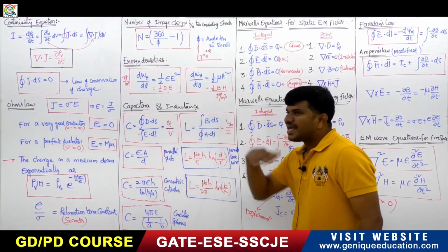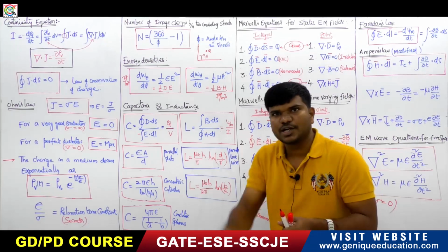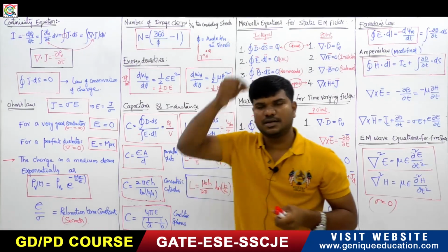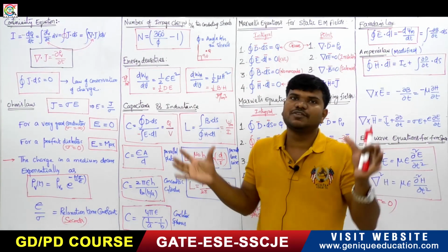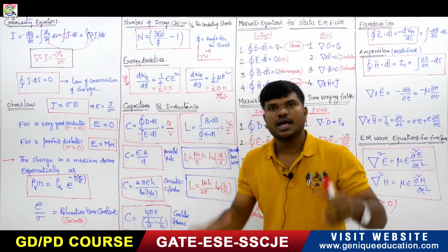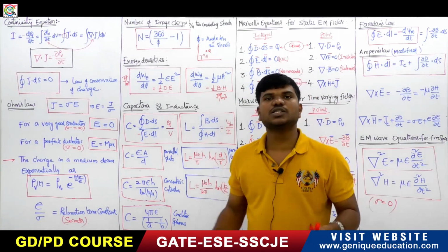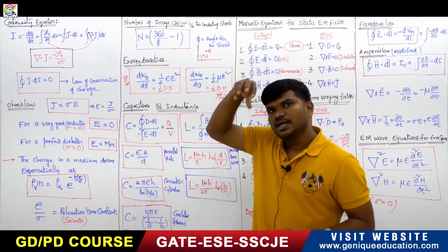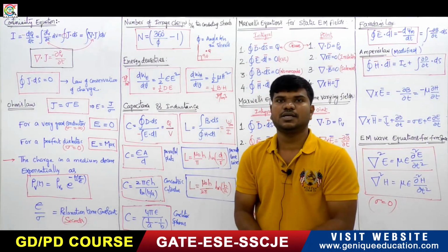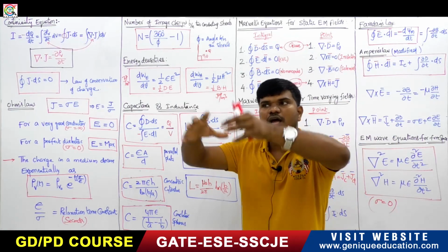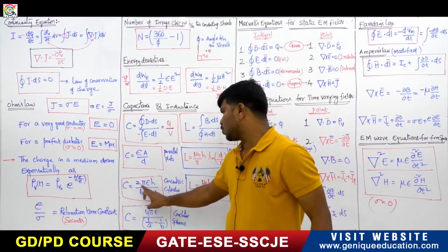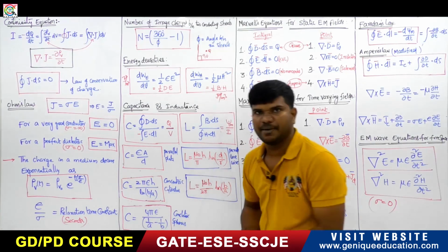Suppose you go to the coaxial cable. It is equivalent to the concentric cylinders geometry, right? A coaxial cable is nothing but one conductor inside and one conductor outside, so there will be an inner conductor and an outer conductor. It is just like concentric cylinders. If you consider the inner one as one equipotential surface and the outer conductor as another equipotential surface, there exists a capacitance between the two conductors. So the capacitance is equal to 2 pi epsilon h divided by ln b by a.